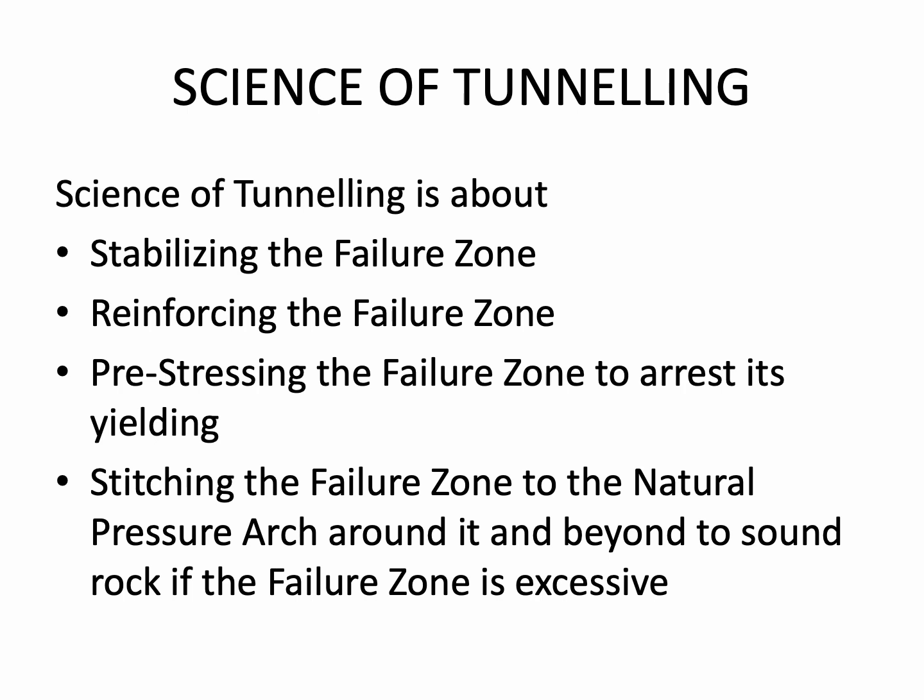Now the science of tunneling is about stabilizing that failure zone, reinforcing that failure zone, and pre-stressing the failure zone to arrest its further yielding.